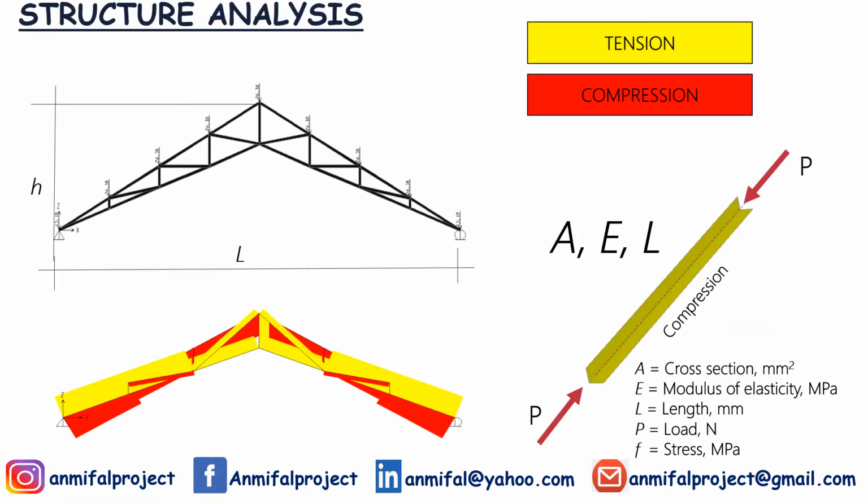As far as we know, in steel structures analysis, we have two types of loads carried in the steel truss structure system: tension and compression load. The compression load can be caused by the gravity load and/or the environmental load such as the wind loads. Usually, the compression load is presented as a negative value, showing that the load is carried toward the cross section of the member.